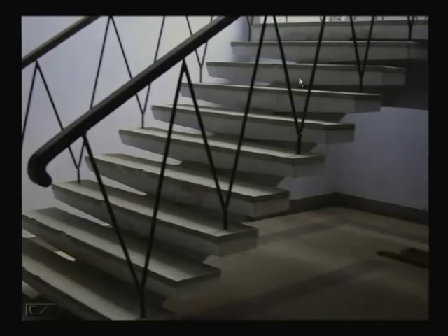Yes, there is a beam here, and over that all the steps are supported. So obviously the first one which I have shown is one kind. This is another kind of staircase which is supported by the beam, and over it the steps are there. These steps are a cantilever beam again.